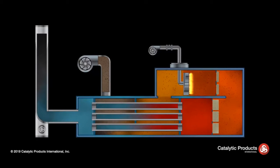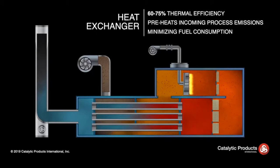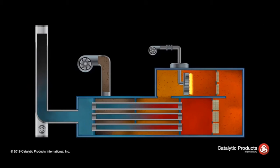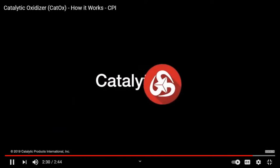In most situations, the thermal efficiency of the primary heat exchanger can range from 60 to 75%. This level of thermal efficiency provides energy to preheat the incoming process emissions, minimizing fuel consumption from the burner system. At the exit of the heat exchanger, the clean, cooled exhaust stream is discharged to atmosphere. The catalytic oxidizer, one of many CPI air pollution control solutions.